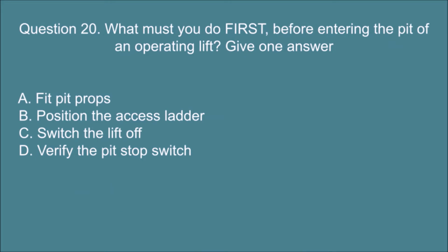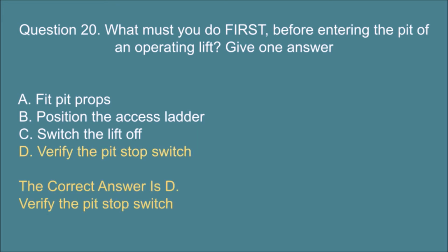Question 20. What must you do first, before entering the pit of an operating lift? Give one answer. A. Fit pit props. B. Position the access ladder. C. Switch the lift off. D. Verify the pit stop switch. The correct answer is D. Verify the pit stop switch.